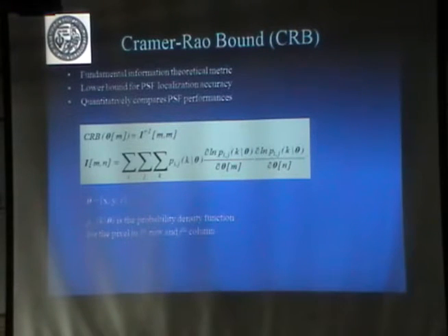So the one that expands the most with temperature, right? You say the alcohol? Okay. So alcohol is better because for every change in temperature, you get a larger change in distance. You are measuring the distance, you are not measuring temperature, right? You're measuring the expansion of the column. So that's essentially what this is, nothing more than that, just more complicated so you don't understand.